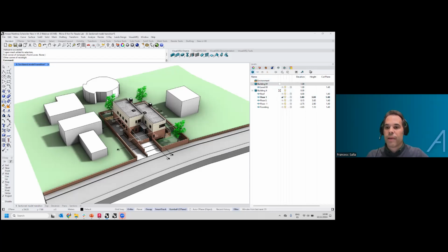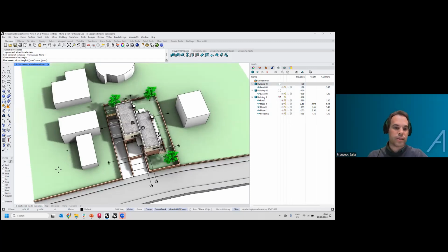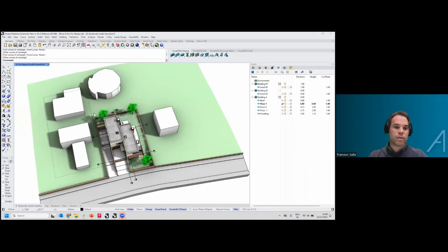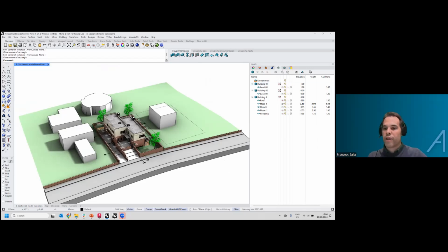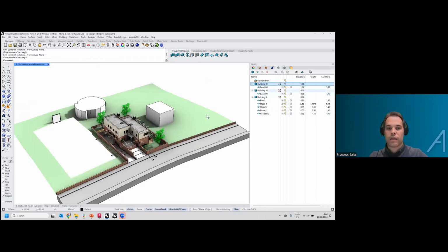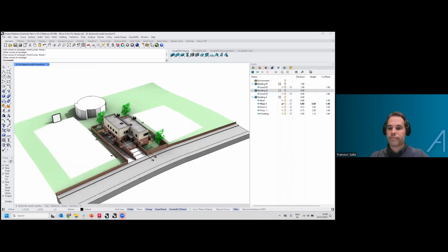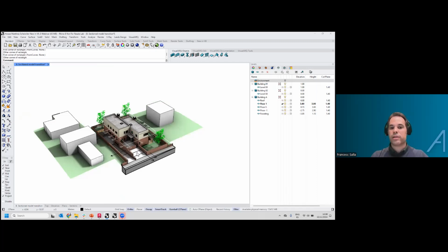And we can add maybe another building, and imagine that we have another construction over this area. So I'm gonna assign a new boundary for that zone, and we will assign also a new boundary for that other part, imagining that there is another construction next to the main building here. So we have 3 buildings right now with a boundary assigned to each one of them. That means that now we can hide each one of these buildings, and then it will hide the area inside the building. Okay. We can show everything back again. And of course, if we hide the environment, all the area surrounding this building's boundary will hide.